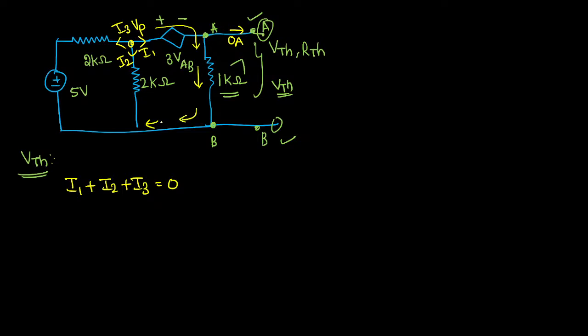Now, how will you write the expression? What you will have is a confusion. Sir, there is a voltage source here, and a voltage VP here, so how do we find the drop across this resistor? One thing you have to understand: this voltage source and the resistor are connected in series. The current you are supplying here will come here only, without changes. That happens only in a series circuit. So, in a series circuit, by interchanging the position of the elements, you cannot change the property.